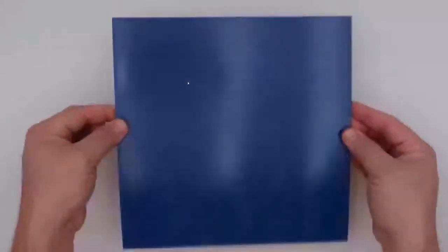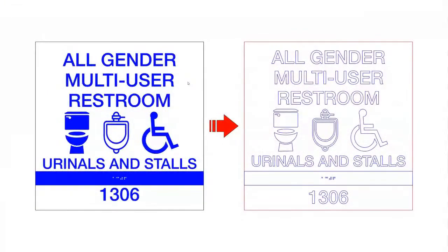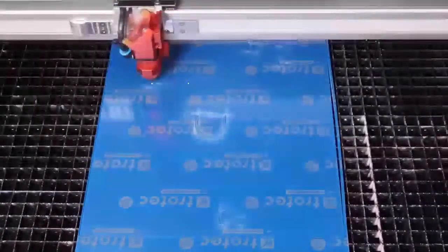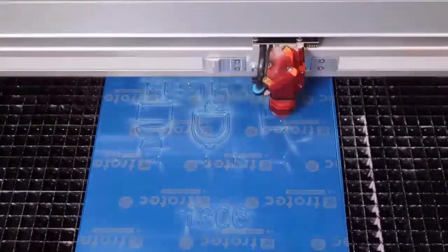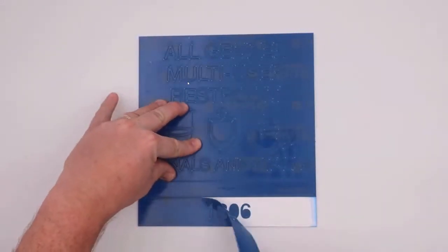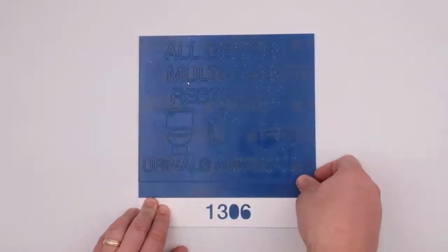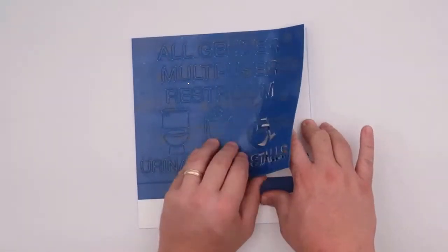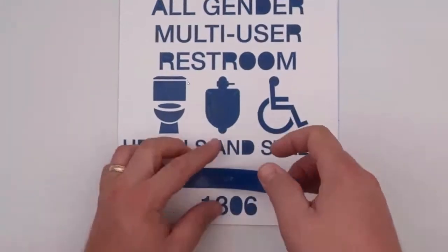All I'm going to do is adhere the two together, peel the double-sided tape, and then take my file, convert it to an outline using the blue for cutting one layer and the red to cut both layers. The laser is going to cut everything in place. It's cutting through all the graphics, the logos, and all the details at one time, cutting one layer and then two layers. Then, as long as you don't wait too long, since the adhesive doesn't adhere over time, you can just grab a corner and peel it up. This is what makes this type of sign so advantageous.